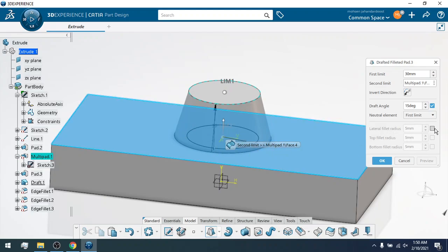The next thing is that the software gives you the option to make the fillet some kind of arc shape instead of this sharp edge at the end. You can make it with some radius. So if I select, it should be the bottom radius. If I select this one, you can see that instead of that sharp end, I get some kind of radius here. We will go over this one for the fillet later in a separate class.